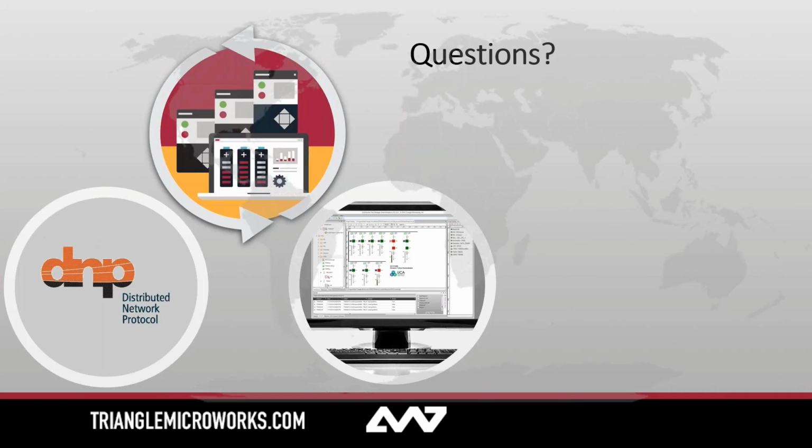Okay, I've got a little bit of a two-part question here specific to 61850. Does the SCD import require any cleansing before import, for example, removing private fields? And the second part to that is, does the 61850 simulation properly simulate the server? Does it simulate multiple report control blocks and changes?